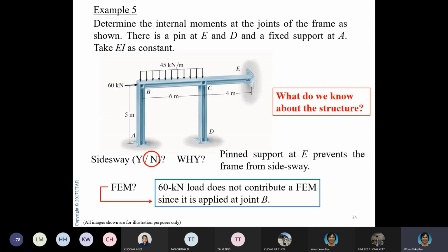And if you're not very sure, you can take something flexible like your ruler, fix it, press it hard to sort of simulate a fixed end. Maybe you put a roller, you make a joint to establish something that you can rotate about the joint, and then you see how the structure works. Okay, try to do that so that you can have a feel of the structure.